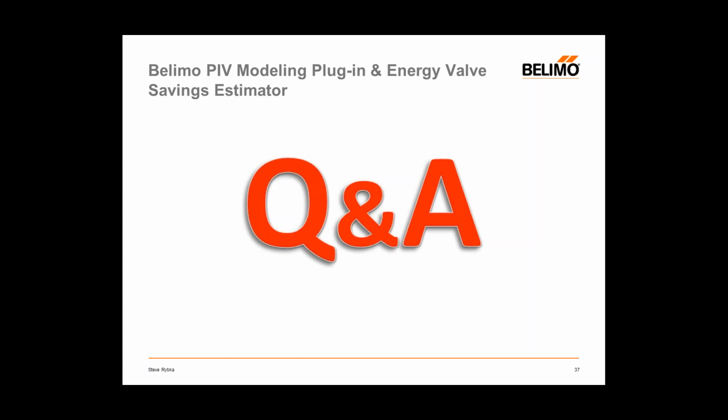Where can you find the information needed to fill out the Home tab of the Belimo Energy Valve Savings Estimator? Well, most of that is manufacturer's equipment data, and some of it will be on the design build or as-built drawings that were put together at the end of the installation of the project. You can also use the I buttons. The I buttons are very helpful on the home screen to help you figure out where to get the information and what information is really pertinent.